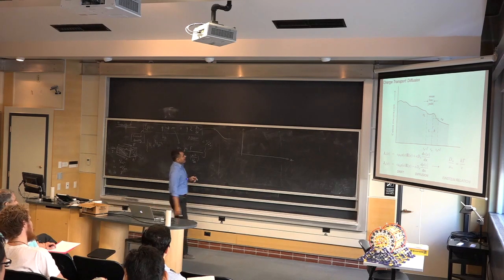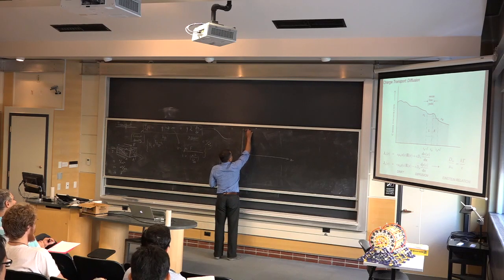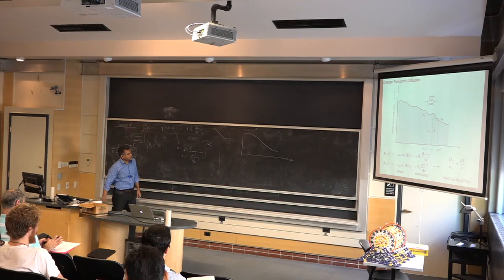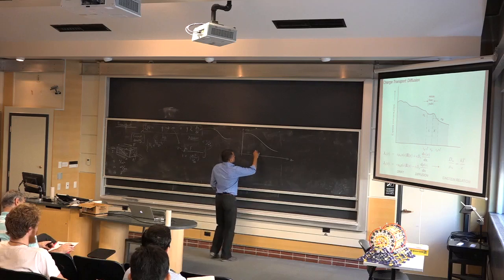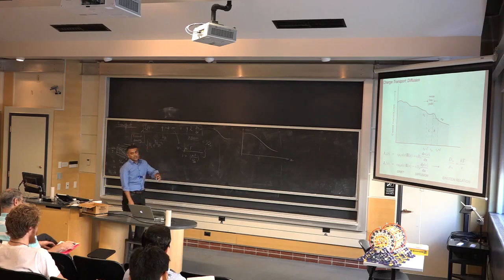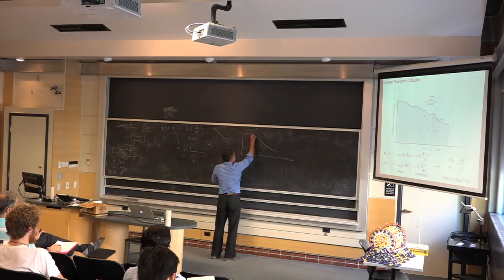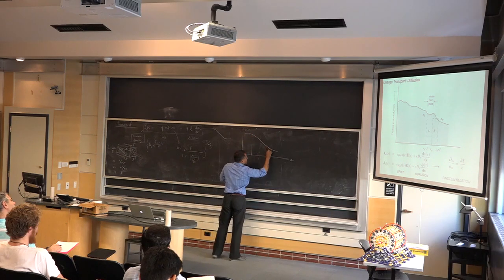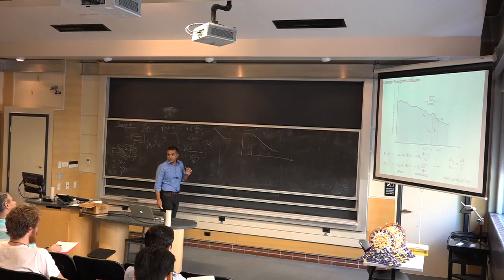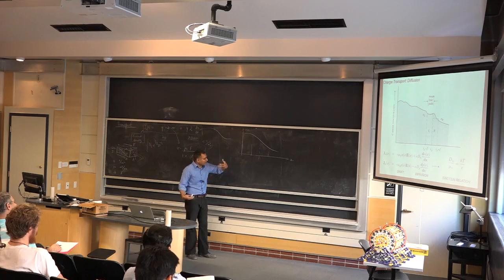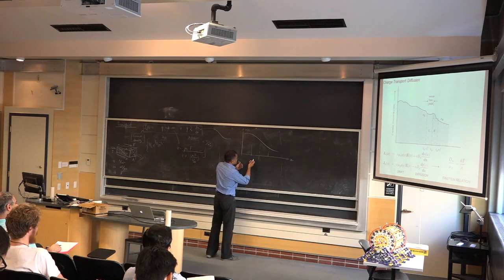So I can plot that N as a function of x, and let's say it does something like that. So the electron density as a function of x is changing, and you can ask, is there an effective current? The interesting question is that I have no electric field in that region, at least right now. It's just that I have a lot more electrons here than here. This is just a density game, right? In principle, if you look at the microscopic process, it's just a random walk. This diffusion is very characteristic, and Einstein derived this for the first time.